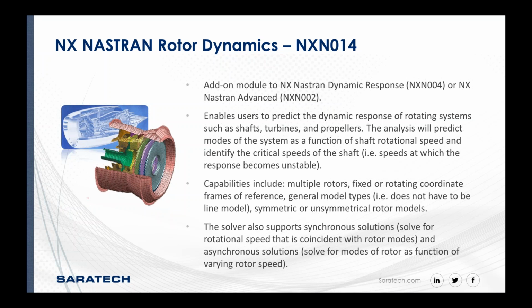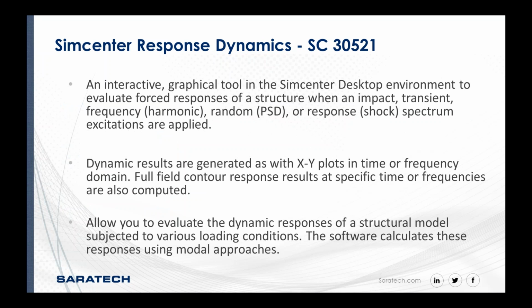If you are using Simcenter instead of FEMAP as your pre and post, there is a response dynamic add-on inside Simcenter. This is a graphical tool inside the Simcenter GUI to do force responses of a structure. It allows you to evaluate the dynamic responses of the structure to various loading conditions. It uses these responses based on modal approaches, so you would solve for your modal analysis, and then it uses these modal approaches to figure out these responses.